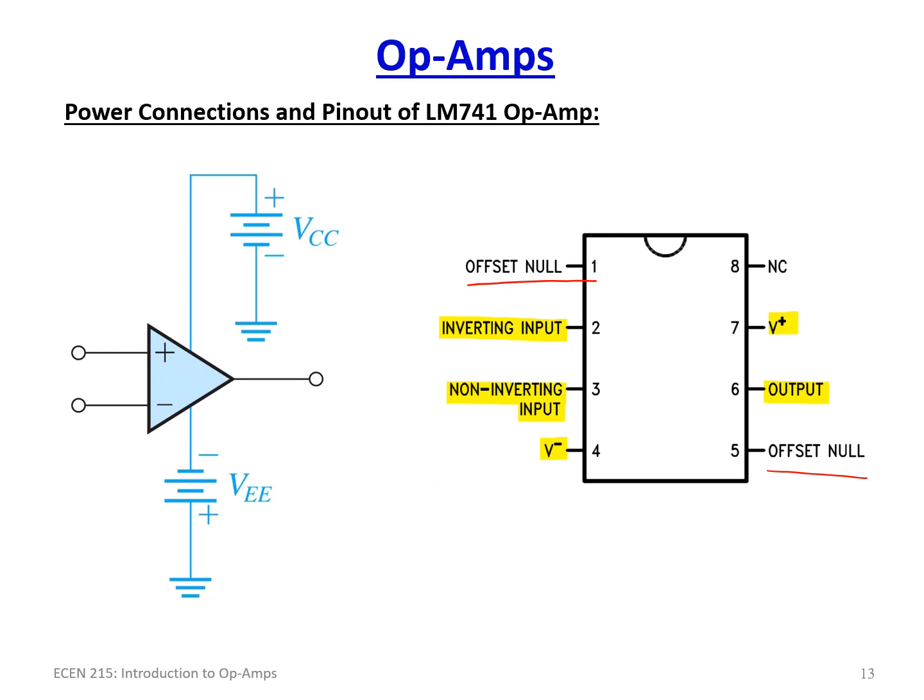If you connect a wire here so that your common mode is the same and your inputs are equal, sometimes the output is not equal to 0, and you would use the offset null pins to adjust for that. In reality, that's usually not too much of a concern. We're talking usually millivolts. If you have a real precision circuit it could be a concern, but for basic instrumentation needs it usually is not a problem.